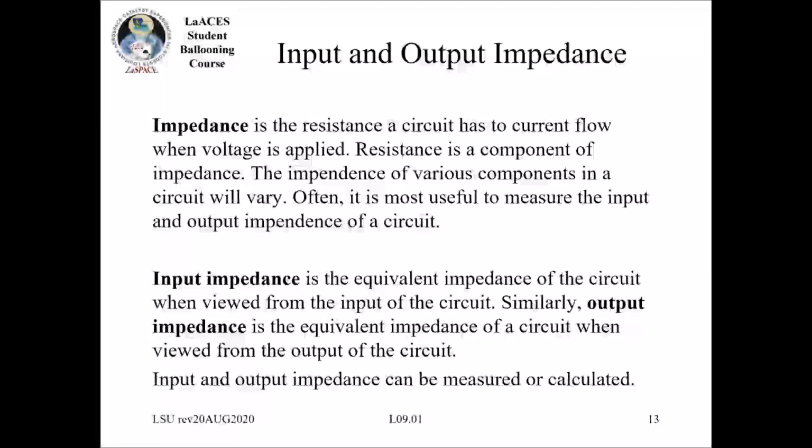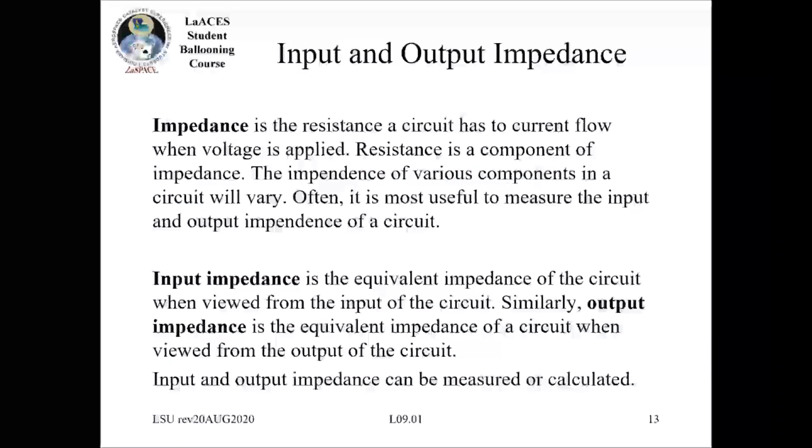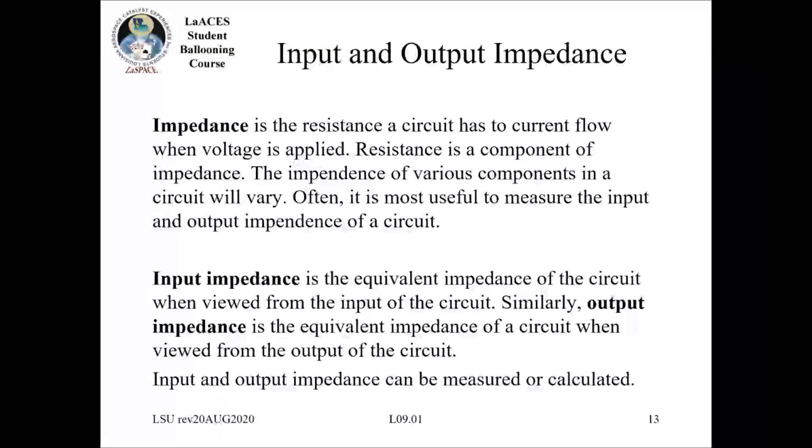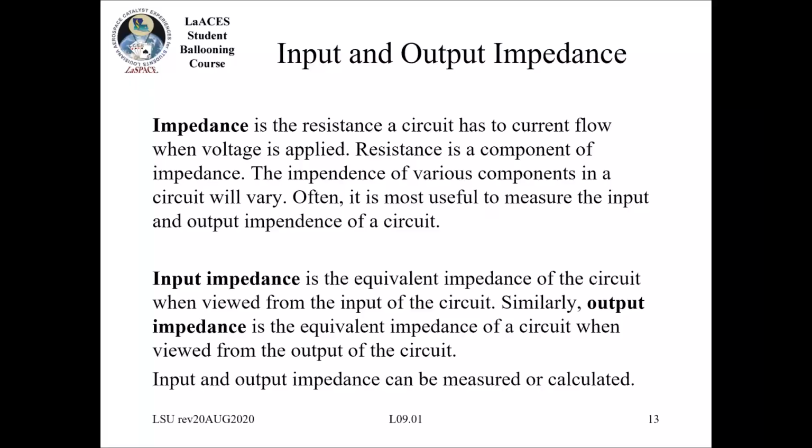But what's important is that your input and output impedance, especially of a circuit, often you want these to match. If there is any kind of mismatch, you will get signal degradation in your line. Or you'll get some kind of reflections, or anytime you have that kind of mismatch, you can get all kinds of noise and issues that get integrated into your signal.